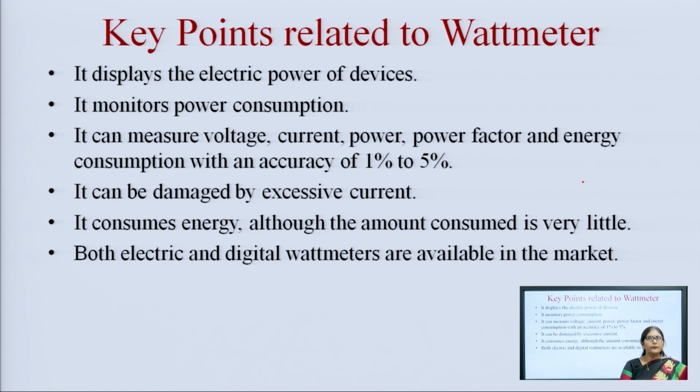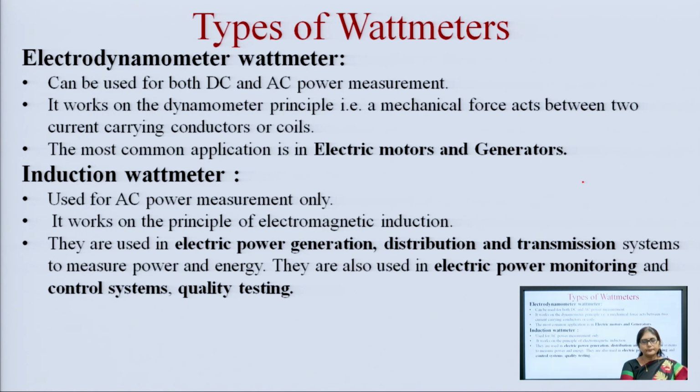Also, since the wattmeter draws current, it consumes energy. Although the consumption of energy is very little, yes, it consumes energy. Then they are available in analog and digital forms. Now, types of wattmeter. Generally, two types of wattmeters are in use. One is the electrodynamometer wattmeter and the second is the induction wattmeter.